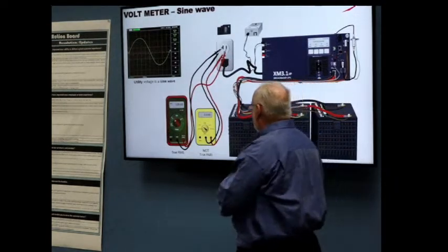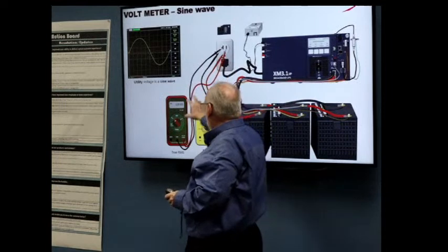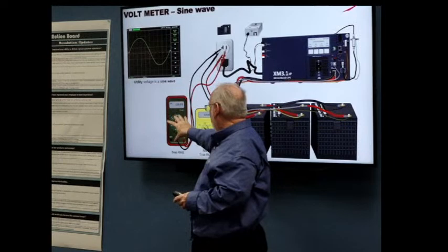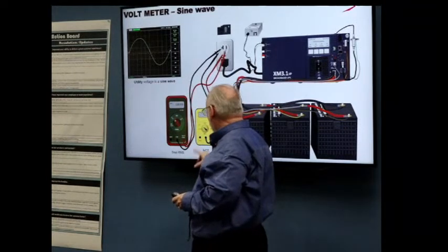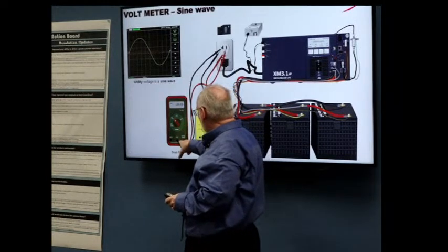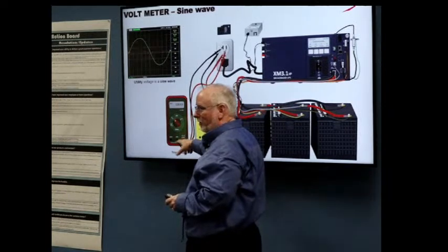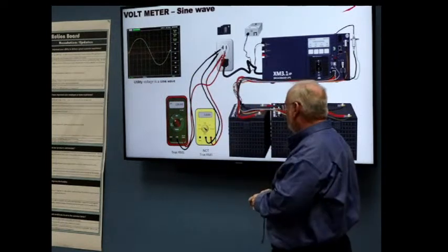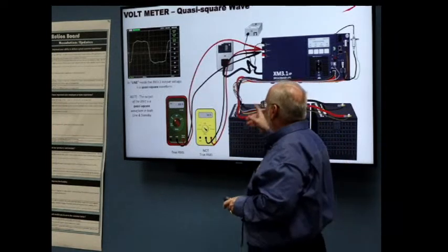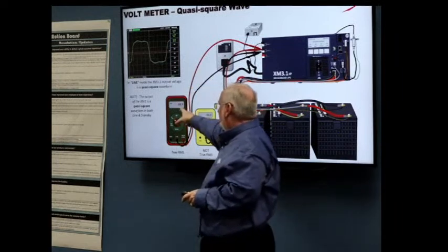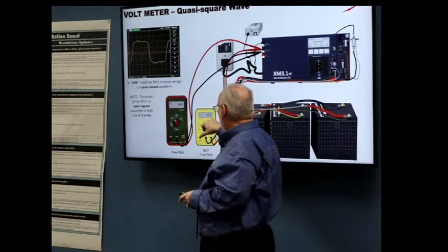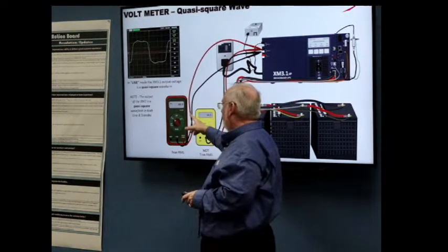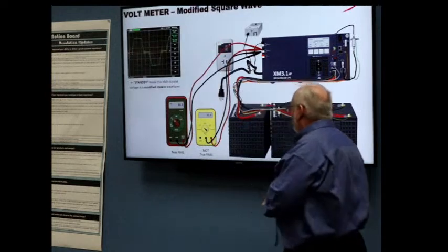When you look at your AC outlet, you may see the same RMS reading out of a true RMS meter and an average meter. The one thing that you want to see on it, and I wish this had it, is true RMS. For an AC sinusoidal waveform, they'll measure identical, or relatively identical. But you look at the trapezoidal wave, that's the actual voltage in RMS. That's what it's thinking it is based on an average. Okay, way off. Invest in a true RMS meter.